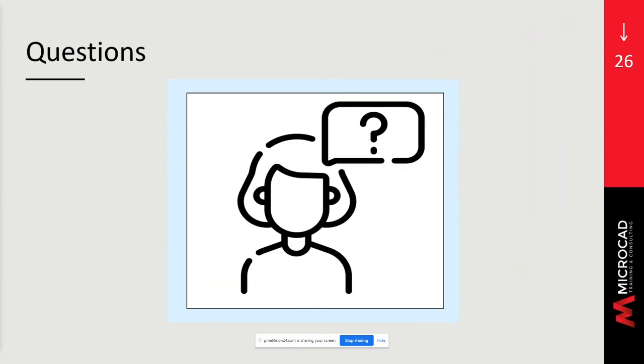But for the purposes that we were looking at, 3 inches was great. When you go interior, then it's usually the number of setups that determine your accuracy. Again, the resolution is device dependent, but the accuracy depends on the way you use it. And if you have more setups so that you have more points in your cloud, then you can increase their accuracy.